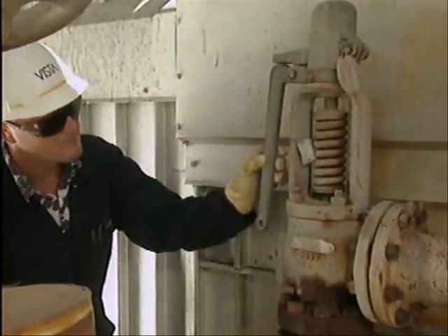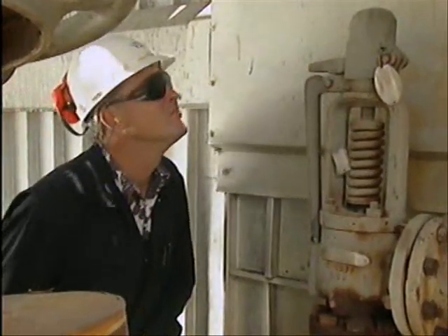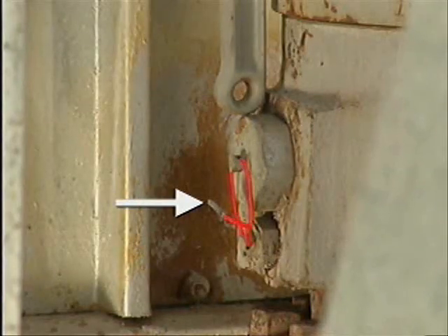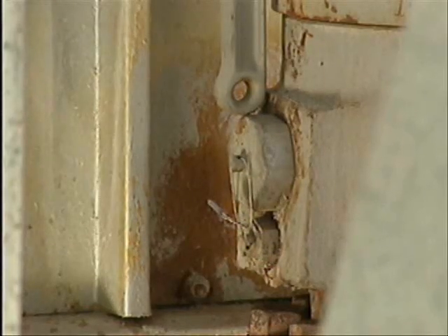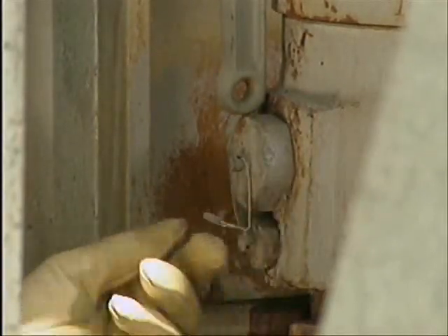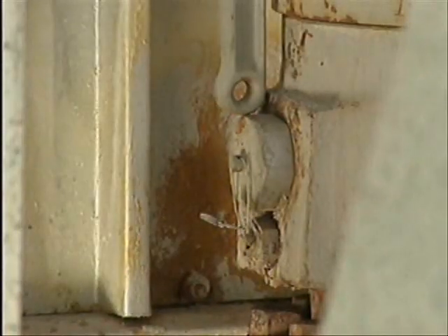For this 2-ring huddling chamber safety valve, first check the lock wire on the adjusting ring pins. The lock wire is fastened in place with a metal clip as the final step in the valve reassembly procedure. So the presence of the metal clip is a sign that the adjusting rings should still be properly set for operation. If the metal clip is missing, or if the lock wire has been tampered with, the valve set points may not be correct. Then you must have the valve taken to the shop to check the adjusting ring positions, and if necessary, reset them.